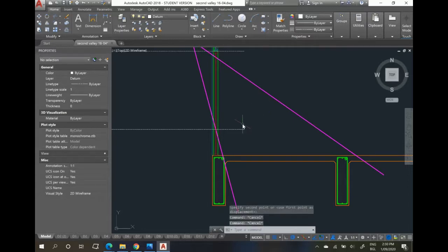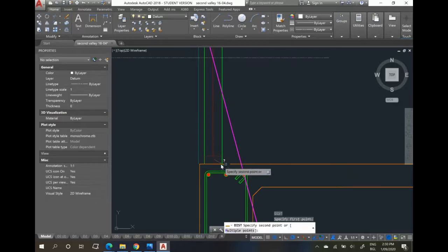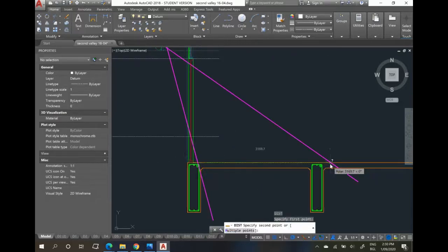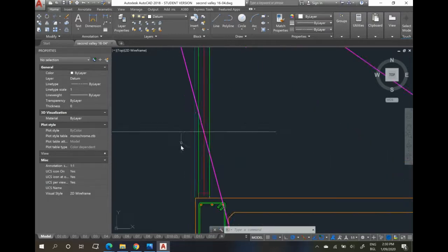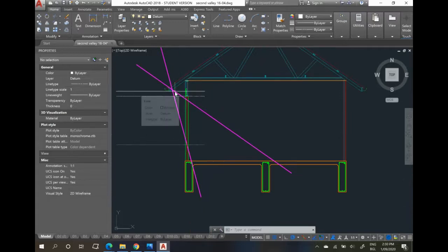We'll go distance and then determine that from, let's say, the inside of wall to our sun penetration, and that's 3.176 meters or 3,176 millimeters. And that's pretty much it for determining what our optimum eaves width has to be to protect the windows in the height of summer, and also then what the resultant solar penetration is for winter solstice onto the floor.